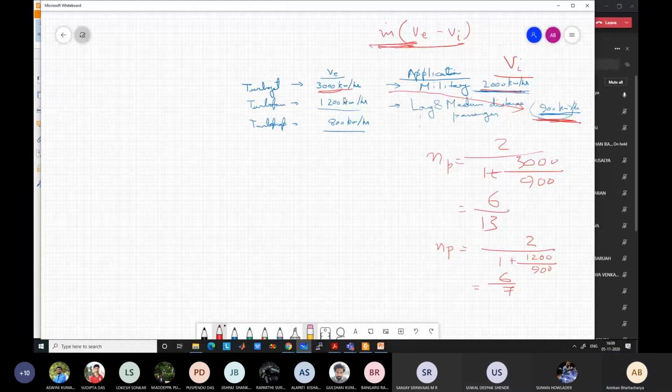Although here we are just thinking in terms of propulsive efficiency, in general the efficiency of conversion, the engine efficiency also, is better for the turbofan in this range. We are not discussing it because my focus here was to show you the effect of propulsive efficiency.